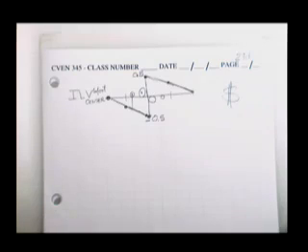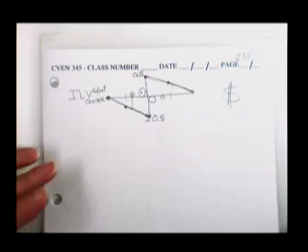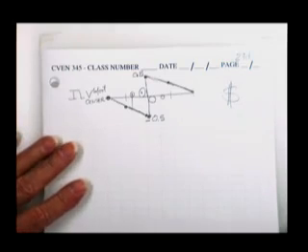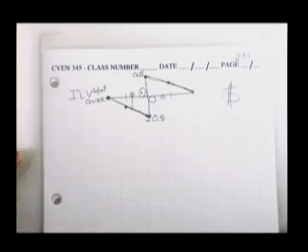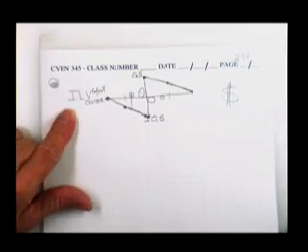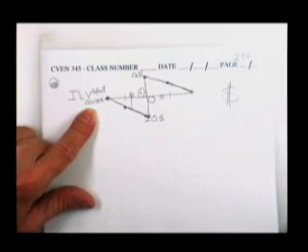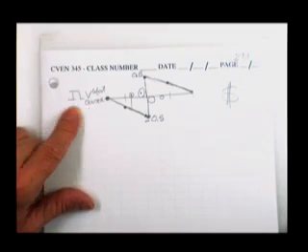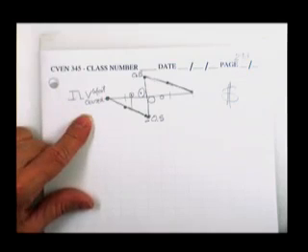If it's symmetric, you won't do the quarter at the 3/4 point, because you're really looking for the maximum shear that's going to be in the beam in a certain region. In this class, you'll be told, give me the influence line in the middle for shear. In the real world, you'll get several of them.